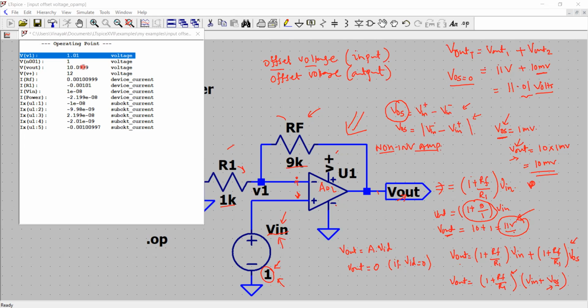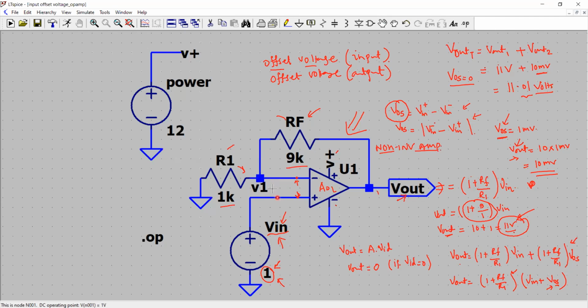So there are manufacturers who manufacture precision op amps with specific parameters such as very low or ultra low offset voltage. So in precise applications for amplification and some other applications, designers often choose an op amp with very low or ultra low offset voltage. Okay, so remember again, the input offset voltage causes output offset voltage. So this is how the case is. Now, what is the reason behind having this mismatch between the two different voltages at the positive and the negative node?